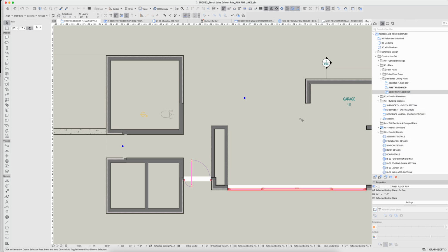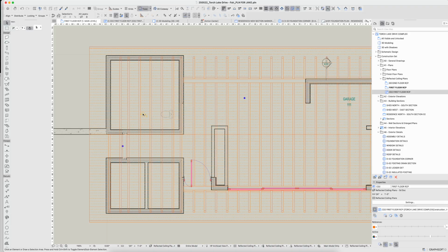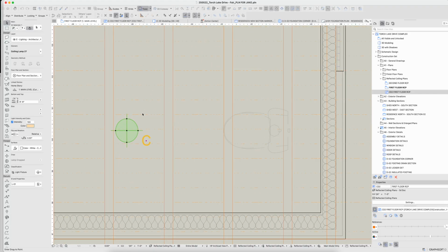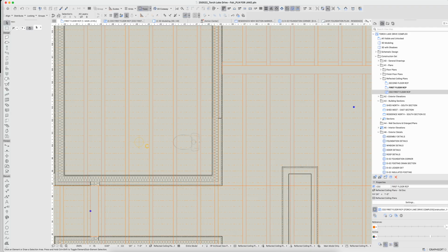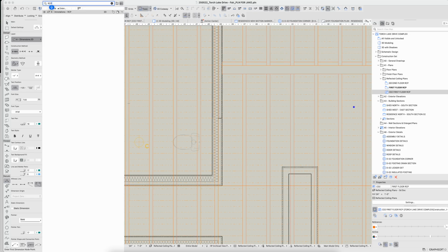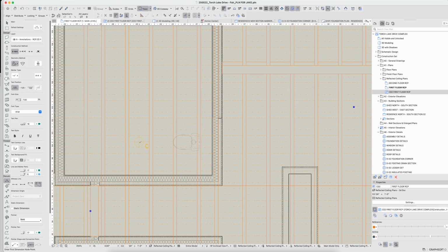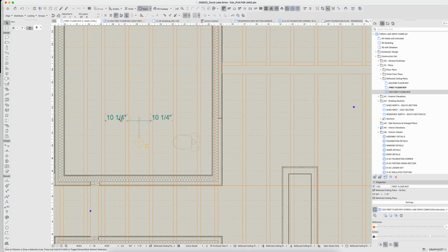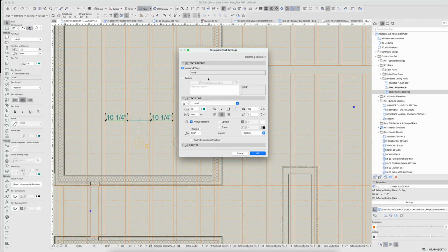So I actually have to show my 3D document as a trace reference, and then that allows me to say that this thing is centered between these two exposed rafters. So whatever that is, 10.25 inches between. If I wanted to dimension this between those, I would put the dimension here in my floor plan. Annotation RCP, get that on the right layer, right? And then I can dimension this in my floor plan directly. So here I can say that this is equal, right?